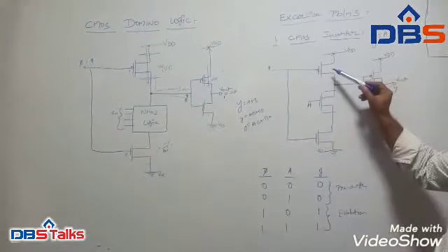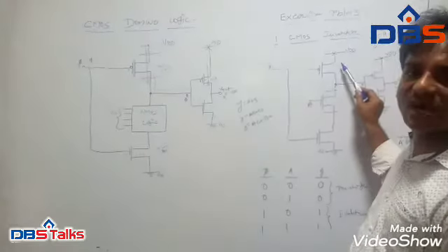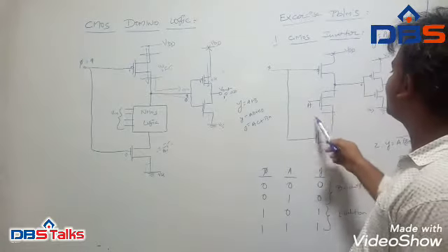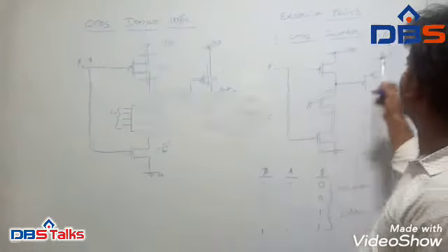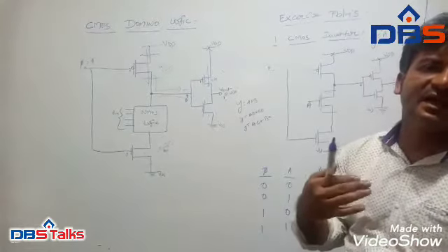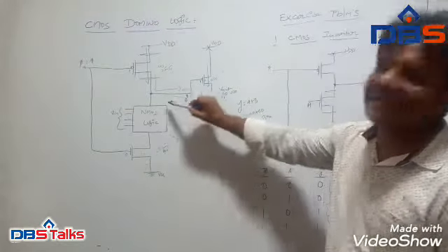So in this design also we have the pre-charge transistor and evaluation transistor. In between, we place the logic functionality we are developing under NMOS logic.